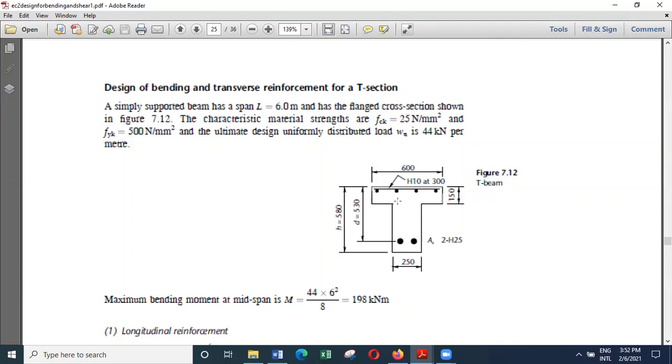So we have to actually check this particular requirement, and that is the amount of shear that can occur here, and whether the concrete can crush in the flange, and also whether we need reinforcement or whether concrete alone can carry it with minimum reinforcement. Or else, if we need some reinforcement, then we have to increase the reinforcement requirement in addition to the reinforcement that we calculate to carry the hogging moment